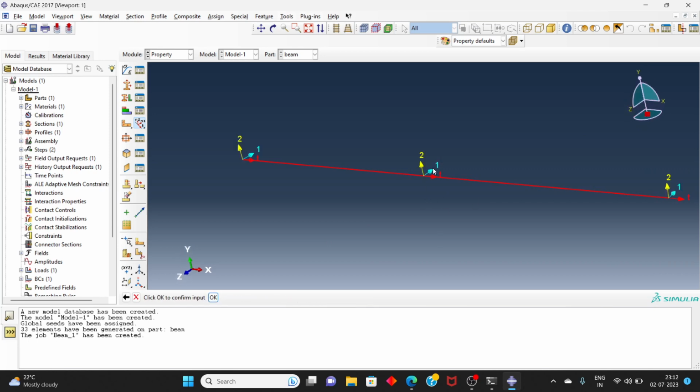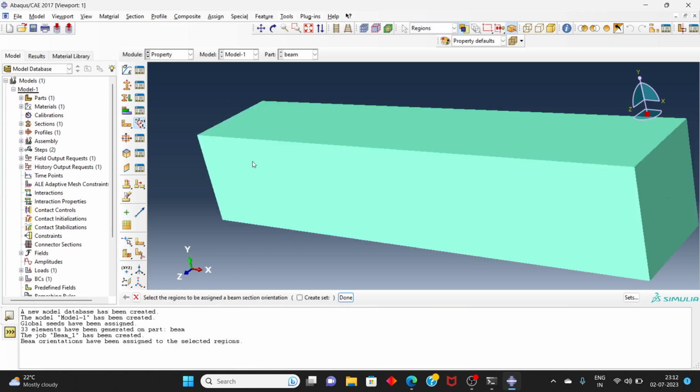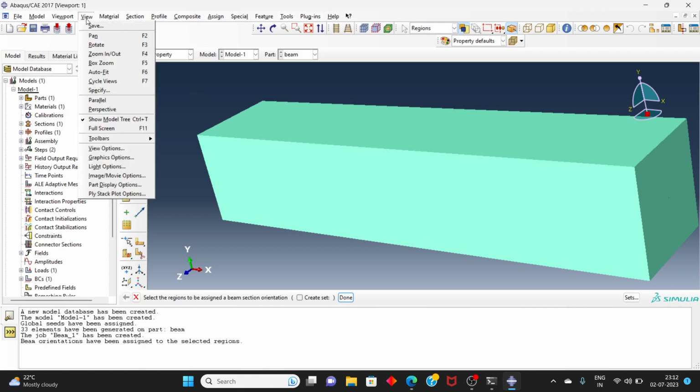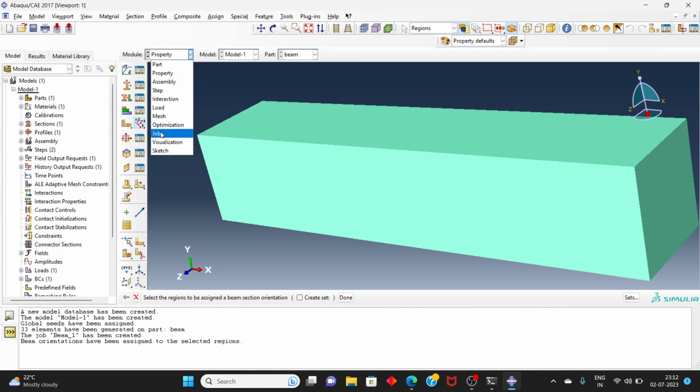We can see minus z direction, 1, 2, and this is the tangent direction. Each cross section is defined in first and second plane, 1 and 2 plane. Okay, so this is why we were not able to see the view option, because we had not defined all the inputs required at that time. Okay, let's just quickly go for the analysis now.